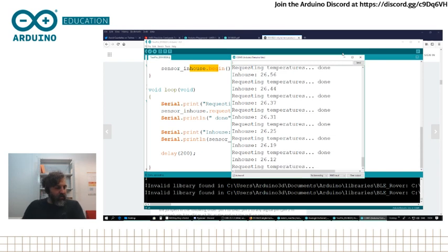So I have 2 more sensors to go. One of them I suspect is going to be super easy, which is this one, because I suspect this is a DS18B20 packaged in a waterproof container. I didn't bring any liquids today, not unlike the previous LiveCast, but it comes with 3 wires. I'm just gonna substitute the sensor I have there with this one. I suspect that red is gonna be power, black is gonna be ground, and white is gonna be signal. I keep my fingers crossed.